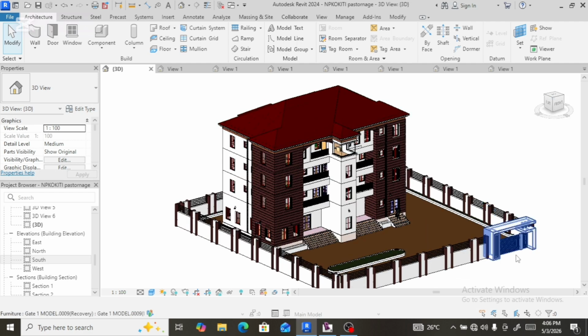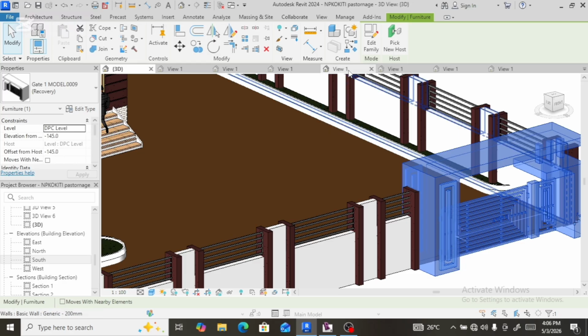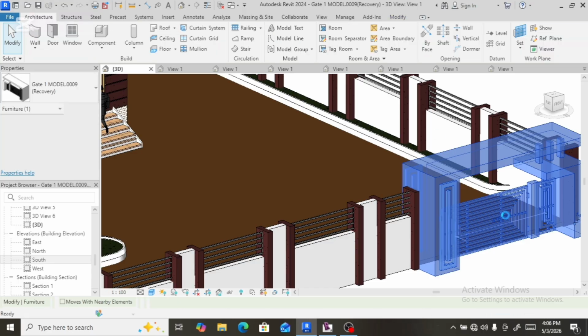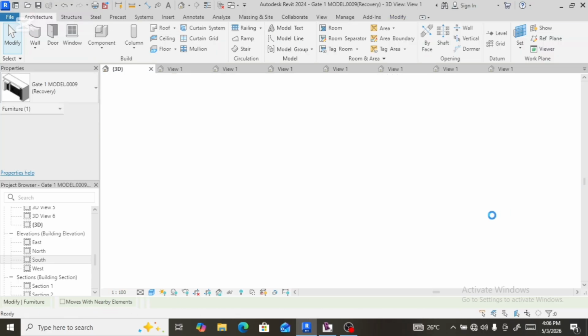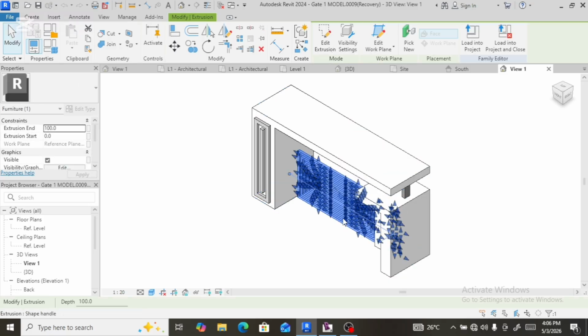I remember that we're not supposed to go in with these gates to Lumion. I was supposed to delete these gates in Lumion. In the family, I would edit family, then edit and remove this particular gate, or copy it out separately and save it at the same time, so that I can be able to open these gates in Lumion. That is the issue.